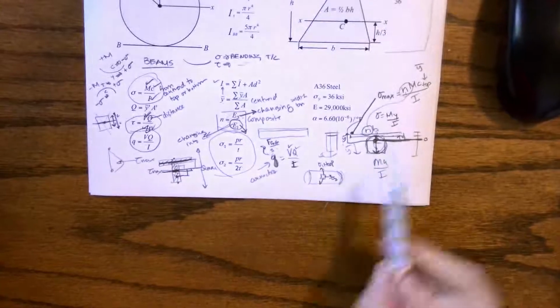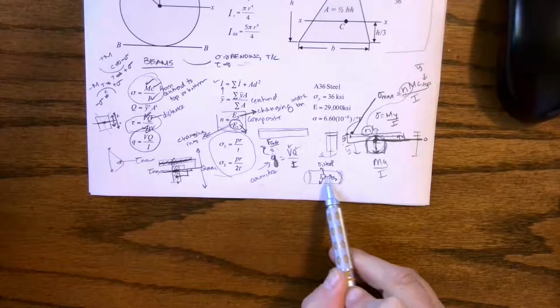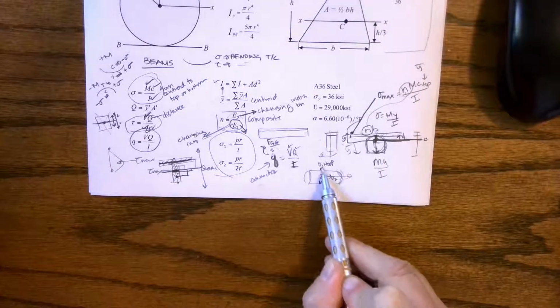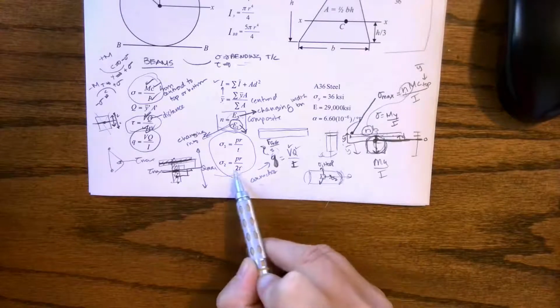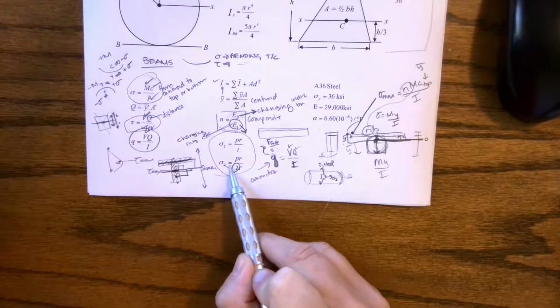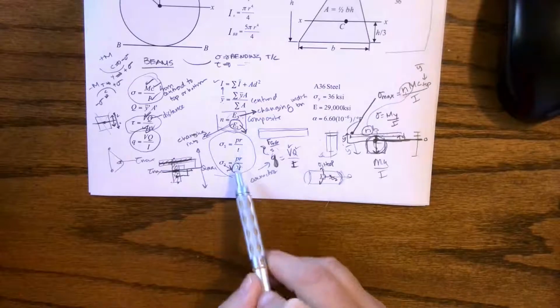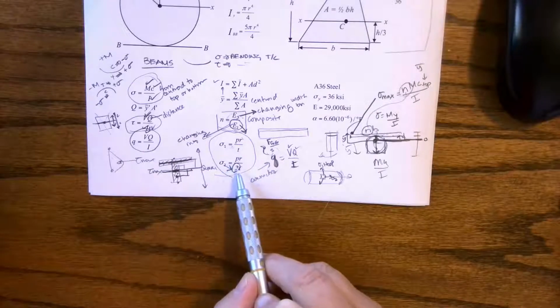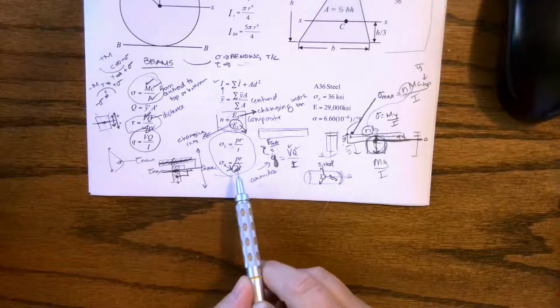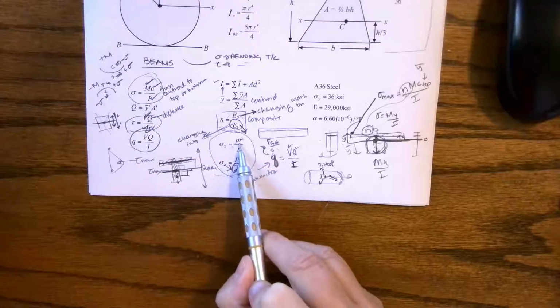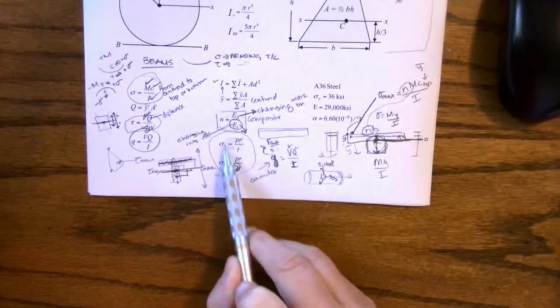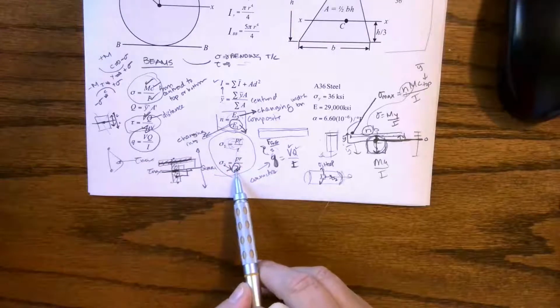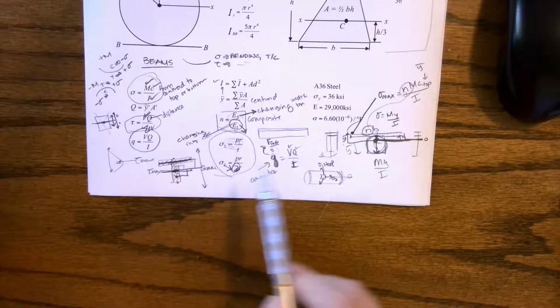And I don't know how you want to remember this. Stress 2 is longer maybe than stress 1. Stress 2 has a 2 on the bottom, okay? And so when we look at these equations, stress 1 is always going to limit, because with stress 2, that 2 dividing factor right here, we are reducing that hoop stress, or the primary stress. We are reducing it by 2.